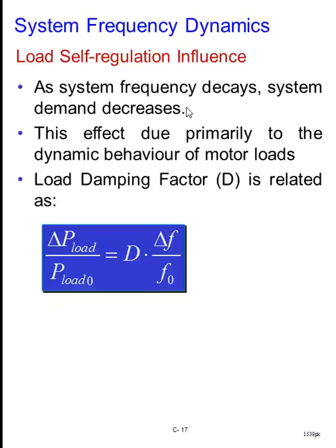So in one way, you have a self-regulation action by the induction machine to improve the frequency towards the nominal value. That's why it is referred to as self-regulation by the dynamic loads, and it could be mainly from the motor loads here. And this is how they are related.